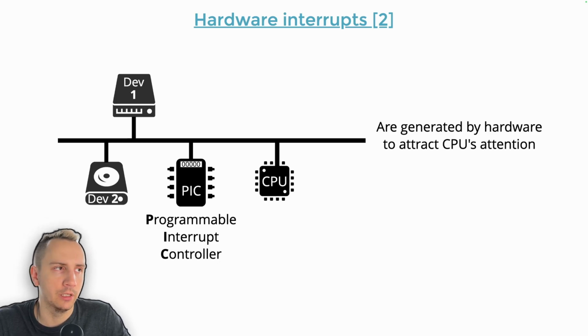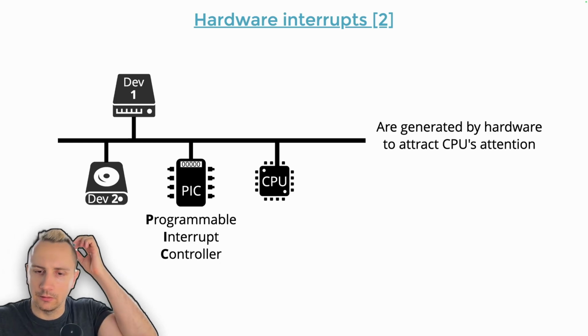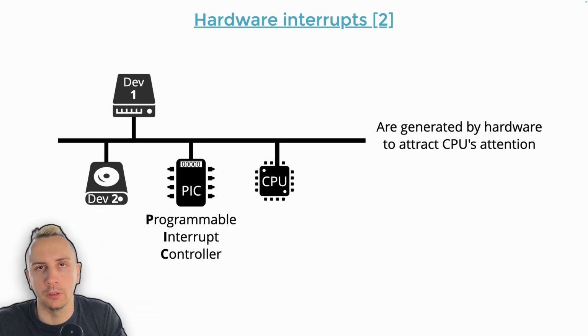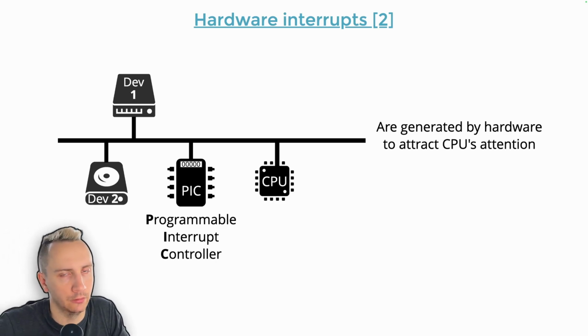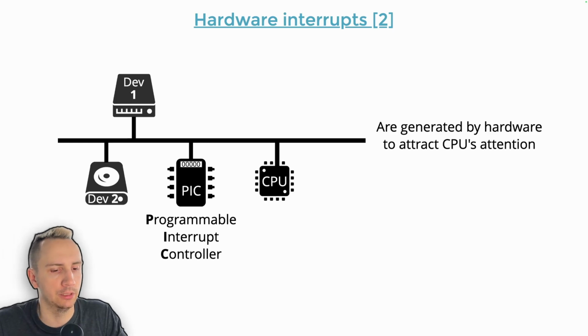To there, each device will send signals over the bus when it wants something from the kernel. The hub will collect all the signals, arrange them by priority, and forward them to the CPU core for handling. And then the CPU core will handle them one by one. It cannot handle more than one in parallel.